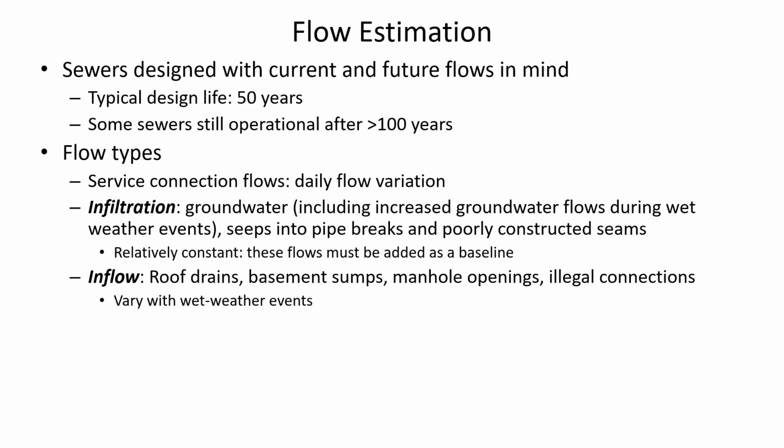But when you have a cracked sewer pipe, the people who are adding wastewater to the network don't notice it, at least not as directly, not in the same way. So when you've got cracked pipes, then groundwater can leak into the sewer pipe. And that's what we call infiltration, when water is getting into the pipe that shouldn't be there.